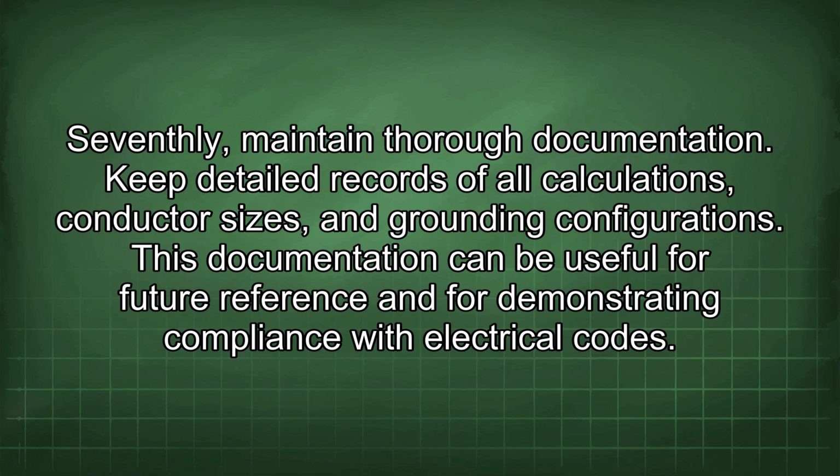Seventhly, maintain thorough documentation. Keep detailed records of all calculations, conductor sizes, and grounding configurations. This documentation can be useful for future reference and for demonstrating compliance with the electrical codes.